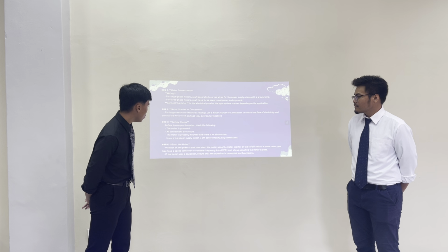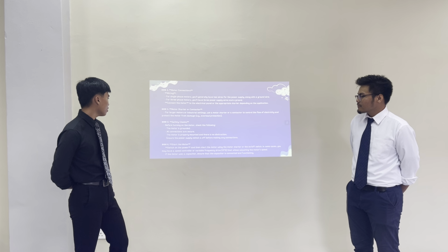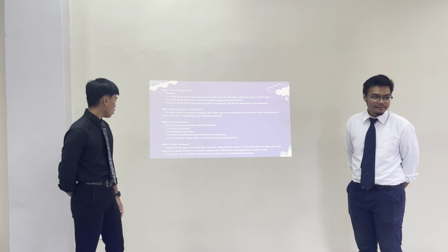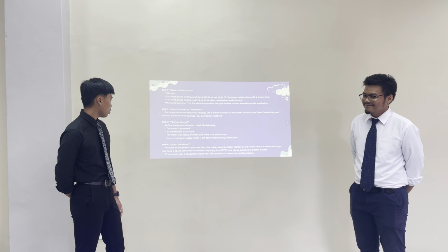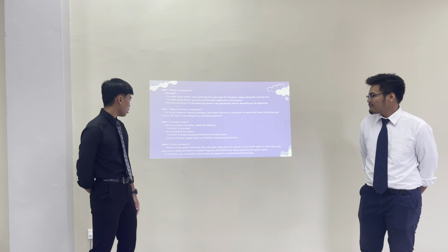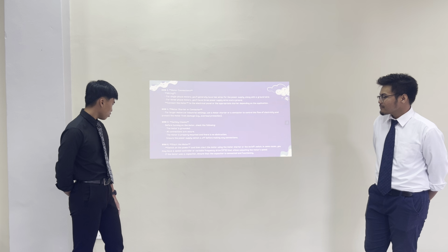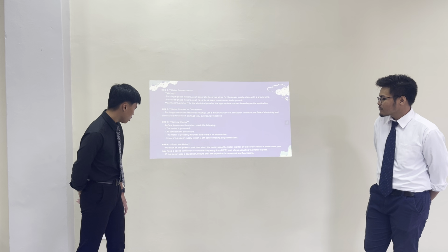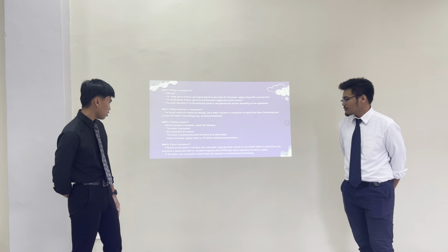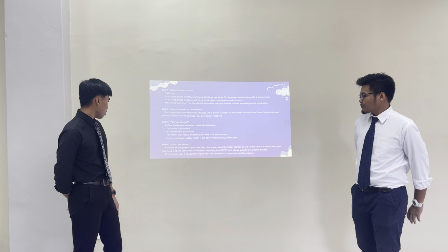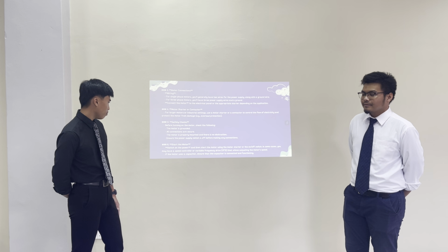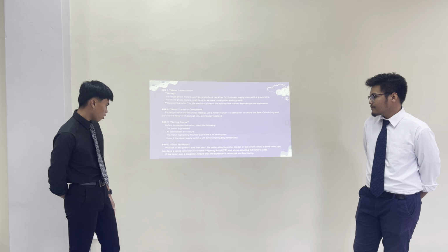Example: overload protection. 5. Safety check. Before turning on the motor, check the following: the motor is grounded, all connections are secure, the motor is properly mounted, and there is no obstruction. Ensure the power supply is off before making a connection.